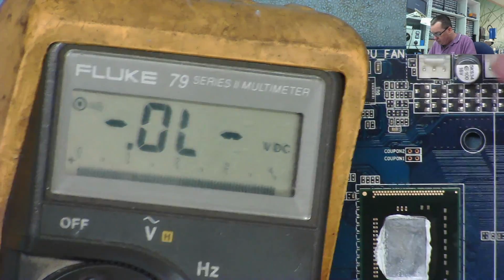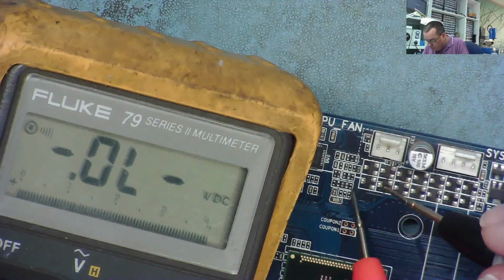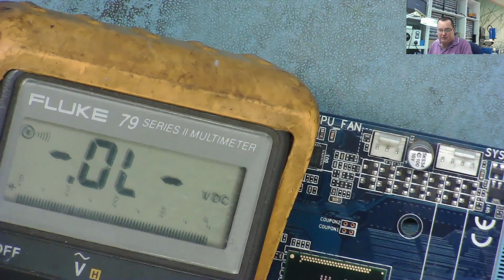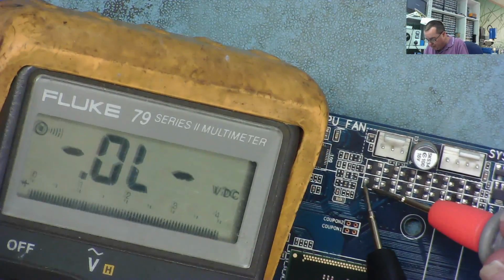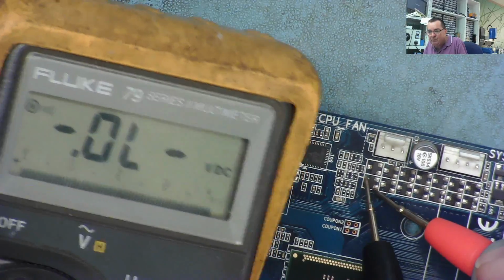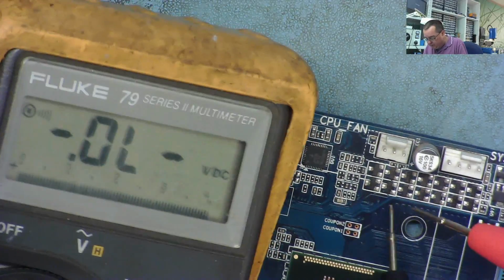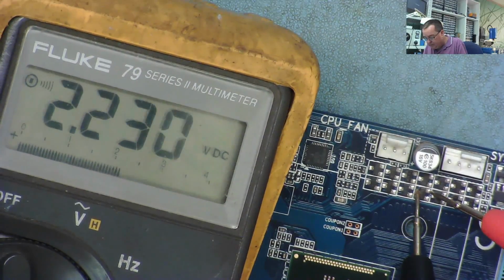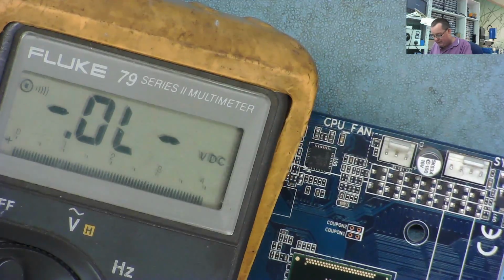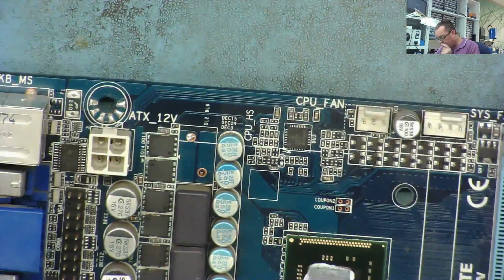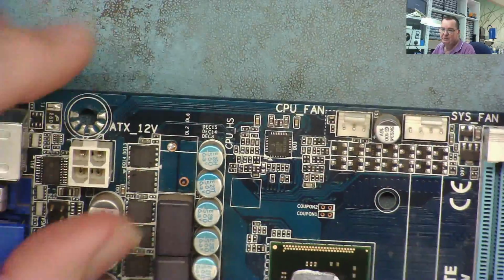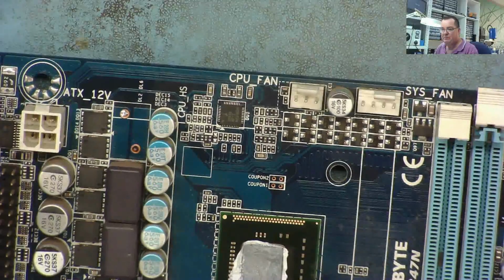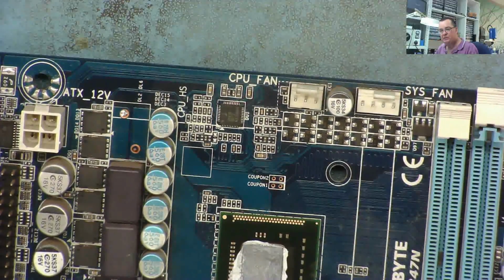So let's have a quick look down here. Look at some of these, just balance this so we can see it. So that means nothing. And bear in mind some of these might be FETs and some of these might be transistors. Also bear in mind the transistor can look like two diodes. So if you don't know what the component is, you probably can't come to any conclusive answer with these type of things. You need to look up the part number to see what they are and then try to test them. So there you go. You can find short circuit diodes quite easily in circuit, but open circuit diodes quite often you can't find. Sometimes you can test them if they're working, and sometimes you can't.